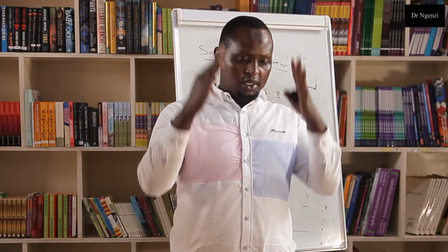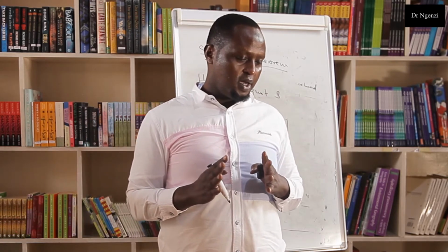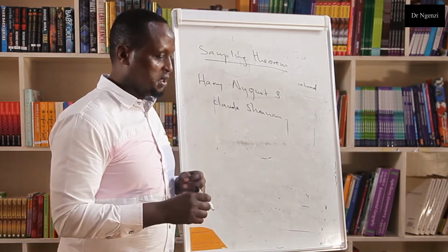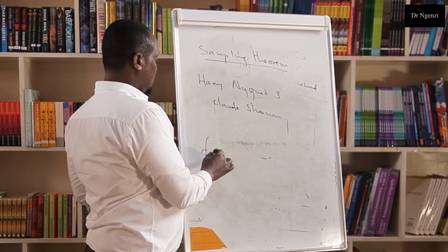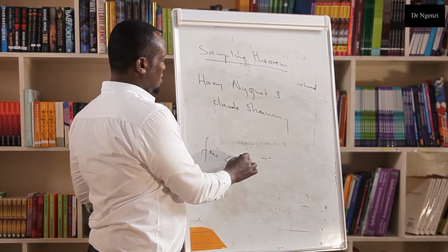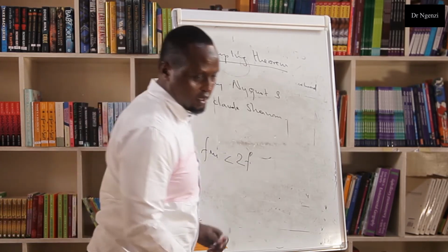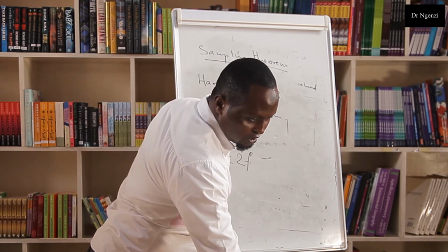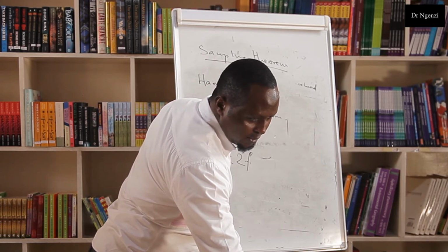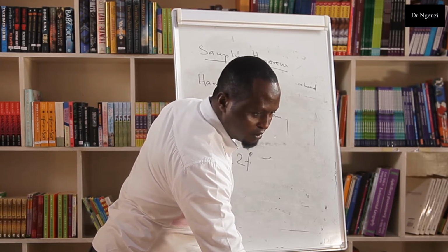So they talked about some of the sampling systems, but one of the very critical conditions was about the frequency. The sampling rate of the frequency component should be at least 2 times the normal frequency.